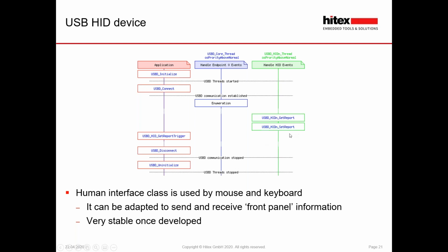These are using the interrupt pipes, so you can set those to poll the endpoints every so many milliseconds. So it's going to be requesting data to be sent up to the device every 40 milliseconds or so, like what state the mouse buttons are, for example. So it's a slightly different approach to how you would use it compared to a serial COM port.